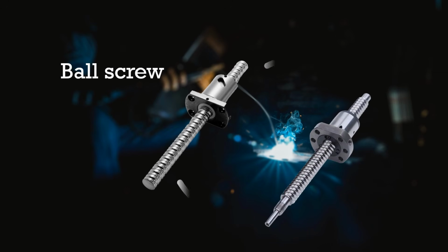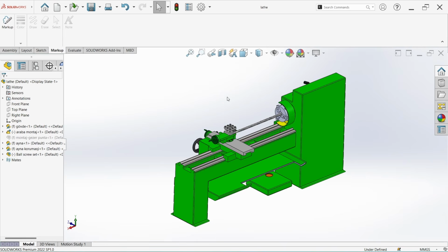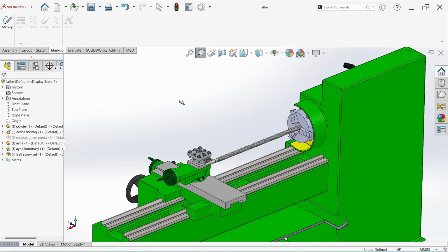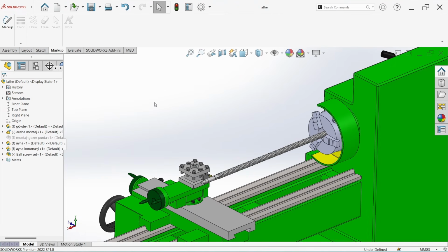We made these bearing steps on a standard ball screw length, and we use the turning lathe machine to make this step. To do that, first we grip the ball screw outer surface in the turning lathe chuck, and then we machine the steps, bearing steps or any other steps. So initially our primary datum should be the ball screw outer surface.